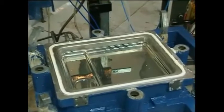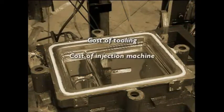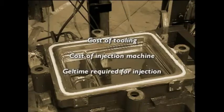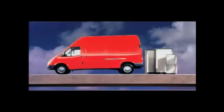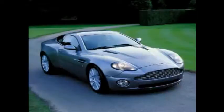The use of RTM can be limited by the higher cost of tooling, the cost of an injection machine, but also by the gel time required for mold filling, which limits productivity in very high volume applications. However, RTM is now a proven technology for fast and efficient production of GRP components.